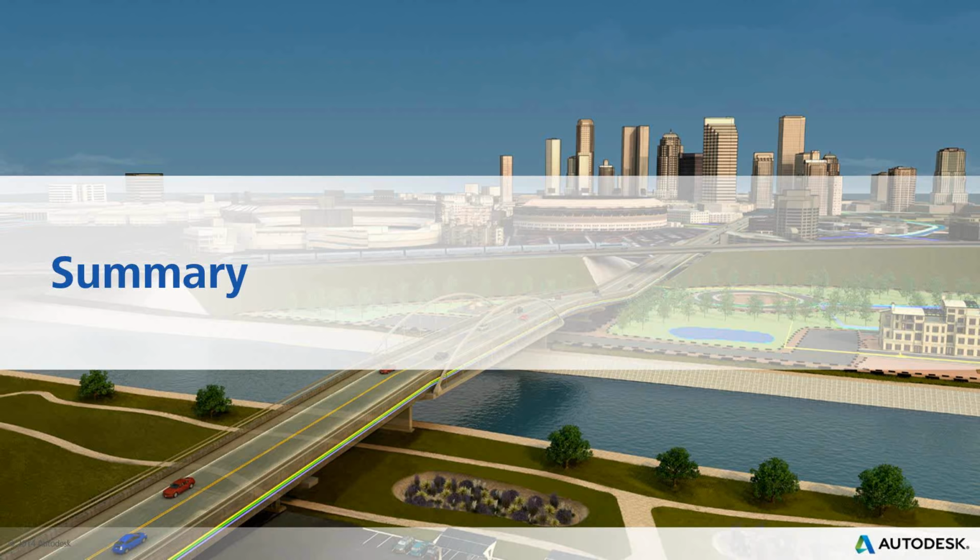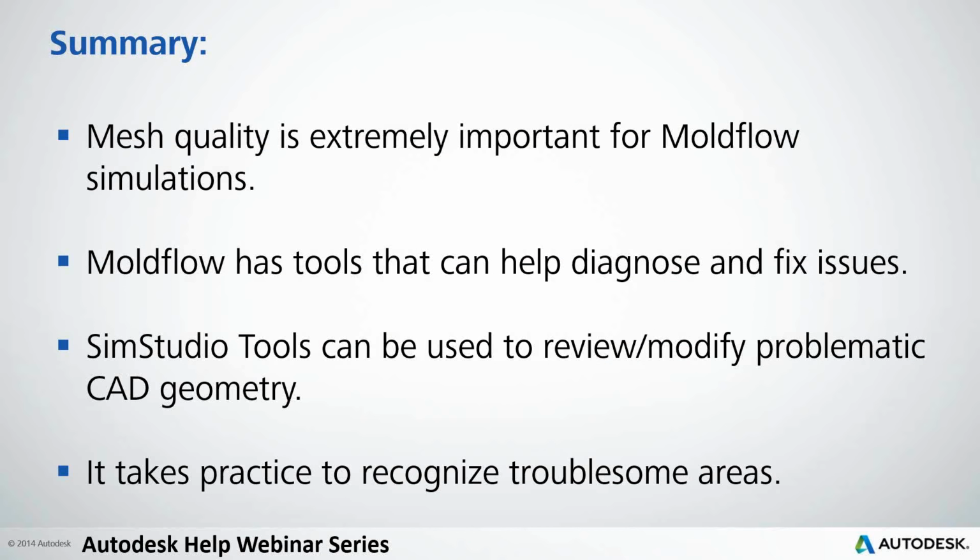And I do see the time is 12:01, so I apologize for going a little bit over today, but hopefully we were able to answer a lot of your questions. Again, in summary, basically we talked about the mesh, how important it is to get a good simulation out of your Moldflow analysis. And Moldflow has those tools built into the analysis, or built into the Synergy user interface, for you to help diagnose and fix those errors.